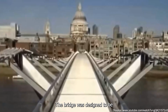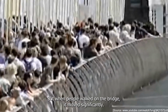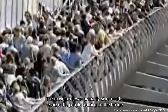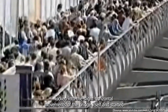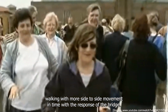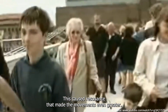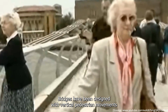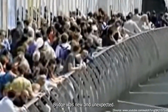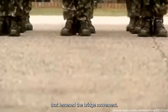The bridge was designed to be a pedestrian bridge across the Thames River, but when people walked on the bridge, it moved significantly. The movement was primarily side to side because the people walking on the bridge locked into the slight horizontal movements of the bridge itself and started walking with more side to side movement in time with the response of the bridge. This caused resonance that made the movements even greater. Bridges have been designed with vertical pedestrian movements in mind before, but the horizontal movement of the Millennium Bridge was new and unexpected. To fix the bridge, engineers put in more horizontal members that lessened the bridge movement.